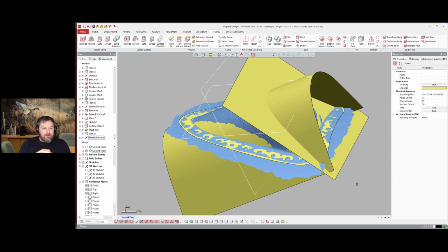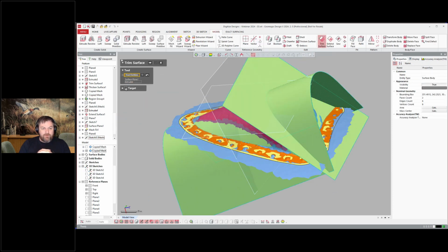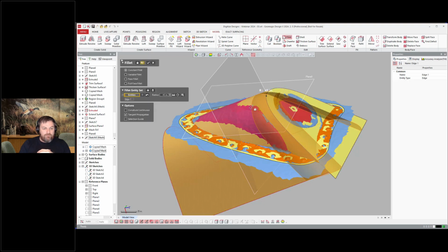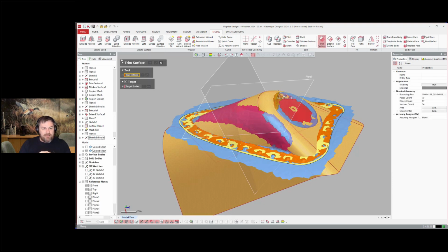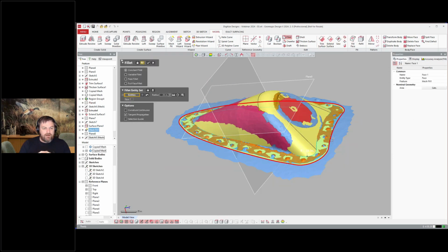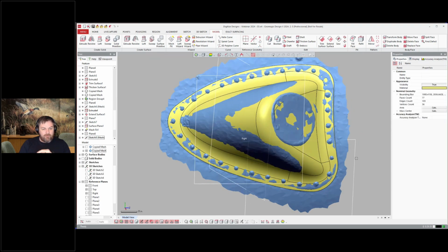So you see, now I'm going to go into the trimming phase, where I'll trim those surfaces together, add a fillet there, and then trim all of these together from there on out. So you see now we just trimmed all those components and added some finishing features like fillets to create that panel, a replacement panel for that side.